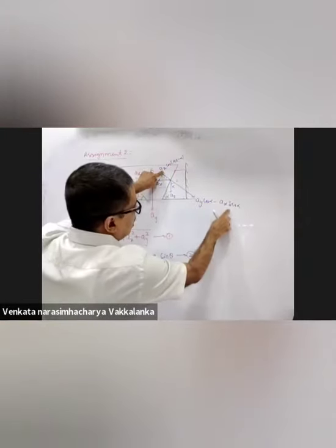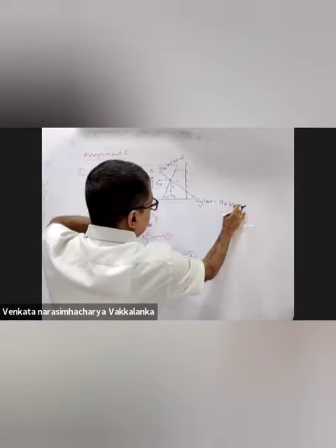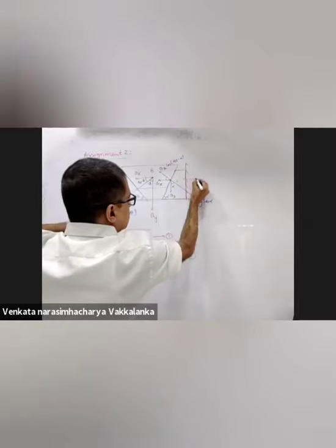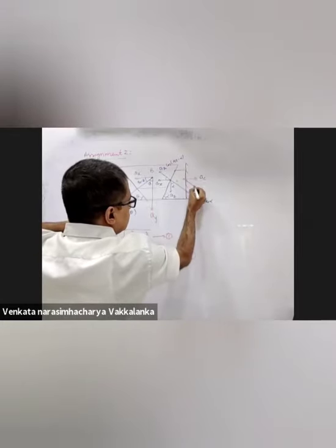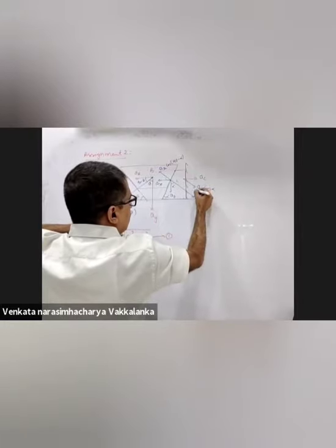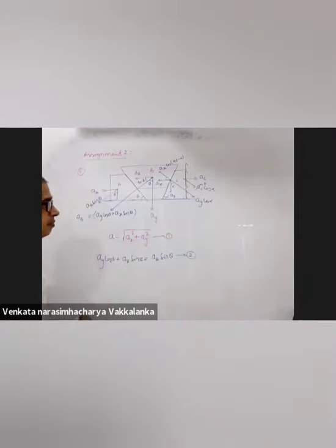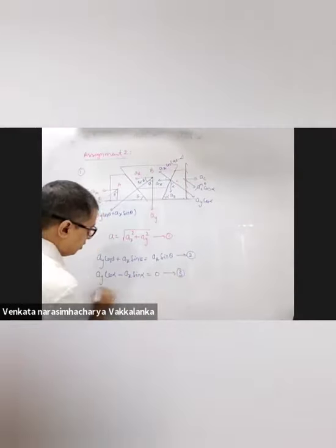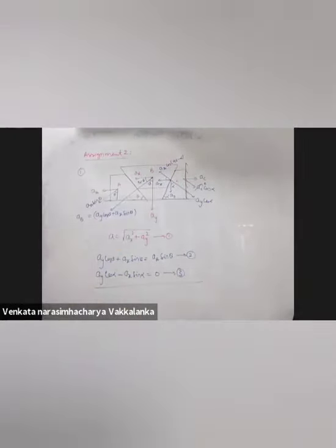AY cos alpha minus AX sin alpha will be the resultant here. This minus this in this direction. What is the acceleration of C? In this direction, AC cos alpha, but AC is 0. So AY cos alpha minus AX sin alpha should be 0, which is my third equation. Three equations, three variables. I should not have difficulty simplifying them.